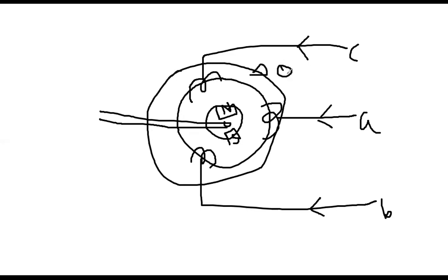This is that phi s. But the difference between this one and the induction motor is that, although I have placed North Pole and South Pole, I did not place any coil on the rotor body. So there is no winding except the damper winding, which I am coming to later. Initially, there are no coils placed. So even though this phi s is being produced because of the application of three-phase voltage on the three sets of coil mounted on the stator body, it is not inducing any voltage. So this means there is no interaction.